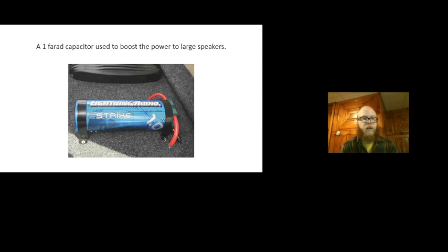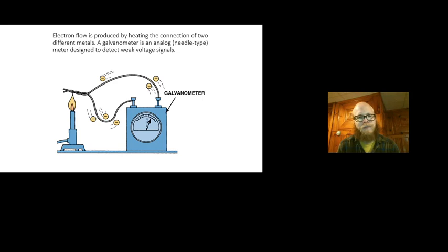I've heard of batteries blowing up when someone has tried to install really big capacitors. And it's just because the capacitor is like a black hole until it's charged, and it just sucks up so much current that it creates over temperature conditions. You might hear people talk about the big glass fuse that comes with these cables, and they'll pop the glass fuse when they're trying to hook the capacitor up, and then they've got to go find another one, and they're not that cheap, and they're all angry about it. They wanted to listen to their cool subs and, complaining. That's how that kind of stuff tends to go.